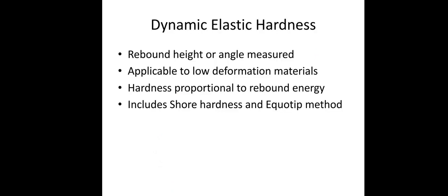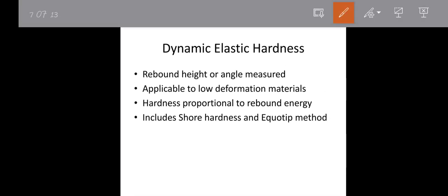Next, we see the dynamic elastic hardness. In dynamic elastic hardness, the rebound height or angle is measured, and it is only applicable for low deformation materials. Hardness is directly proportional to the rebound energy.